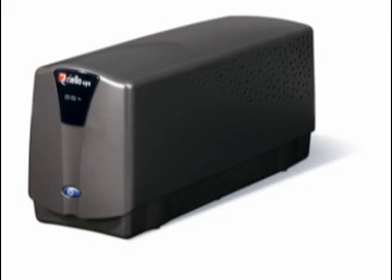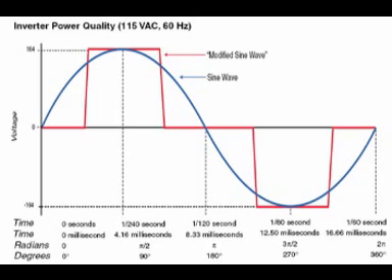Generally, here is how it works. A true 120 volt sine wave is like a circle stretched out over time, moving above and below a reference. Normally, it starts at 0 volts, races to its peak at about positive 165 volts, goes back to 0, then down to negative 165 volts, and then back to 0 in 1/60 of a second.